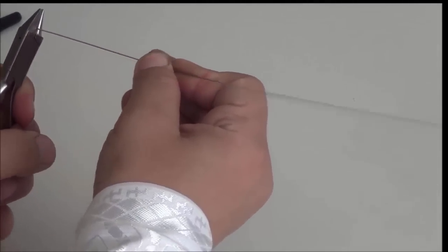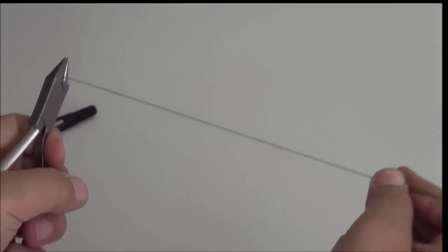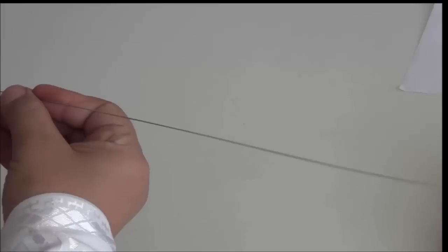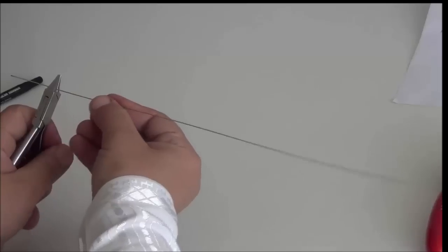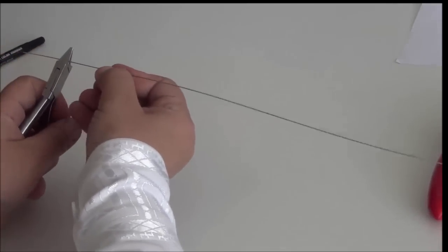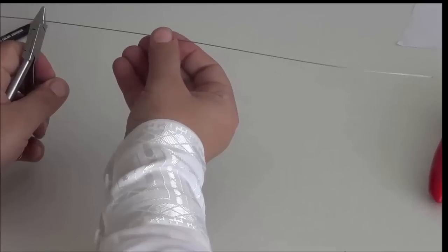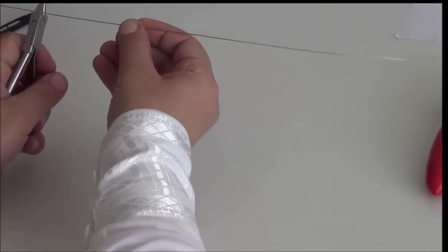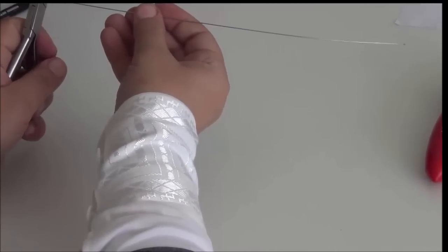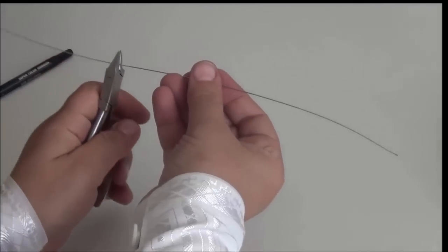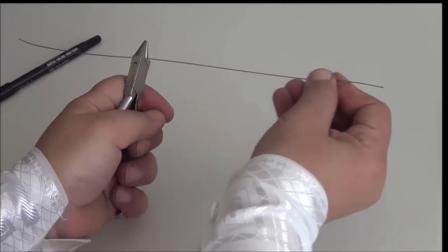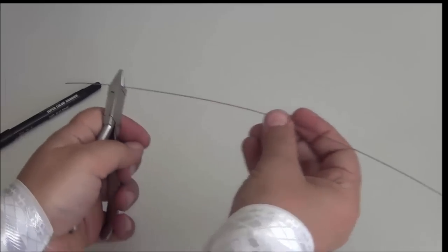And I want to straighten it. I could do it with gentle finger pressure in the opposite direction of the bend. So the wire was bent in the direction away from me, so I'm bending now towards me in a minor and concentrated manner. Whenever I have a straight part, I go and move and straighten the other part. Okay, I observe the direction. I make sure I'm bending exactly against the same direction. So I keep making sure I'm fixing the wire in the correct direction. So as much as possible, I try to straighten the wire before beginning my wire bending.